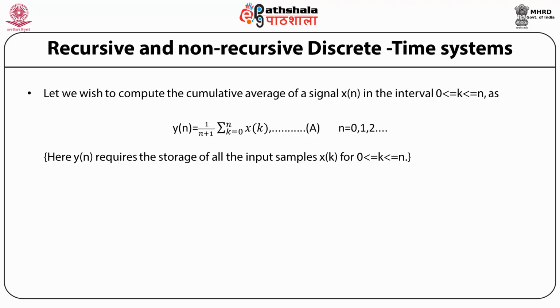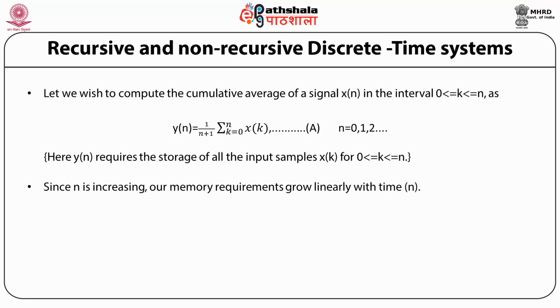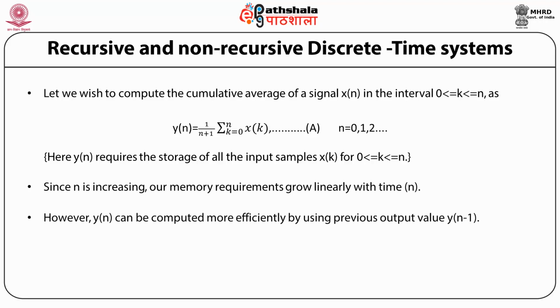And here y(n) requires the storage of all the input samples x(k), for k varying from 0 to n. Since n is increasing, our memory requirements grow linearly with time n. However, y(n) can be computed more efficiently by using the previous output value y(n minus 1).